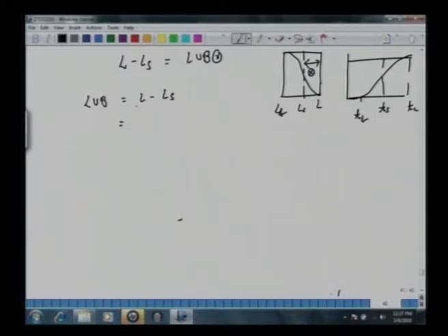What is this length here? Had the wave been ideal, had it reached here, since this area is the same as this, we could have said that now the bed is completely saturated. That means this L is nothing but US, the speed of the wave, times TS, the time at which this area is the same as this area. So make a note here: L is US times TS. Then LS is here, that means this is US times TB.